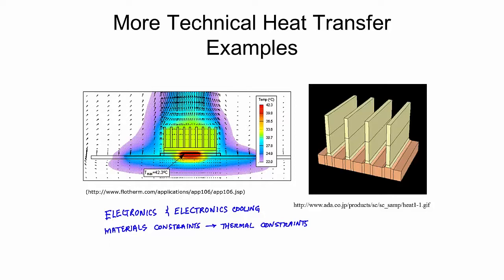And so one of the things that has been done for years in terms of keeping chips cool is to incorporate augmented heat transfer area surfaces called fins to increase the heat transfer rate away from this hot spot where it's oftentimes joule heating inside there that causes these high temperature regions.